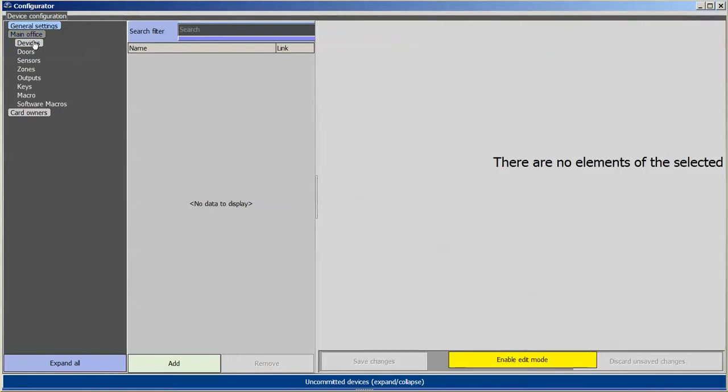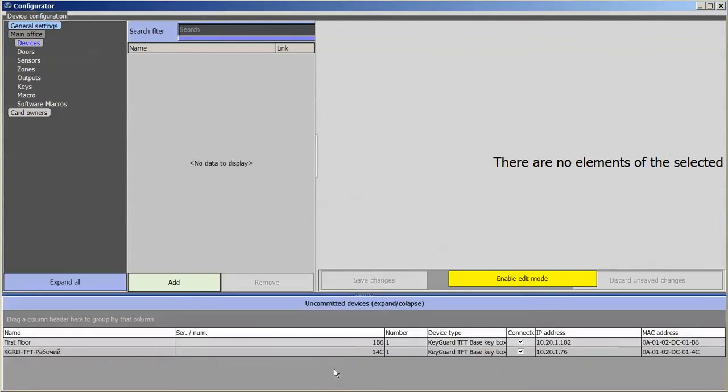To get the connected key system, you should first set up the IP address and the server address directly from the touchscreen of the management system. To open the menu with IP settings, press the Setting button on the power supply unit inside the box. Please read now how to set up the key system in the installation manual.